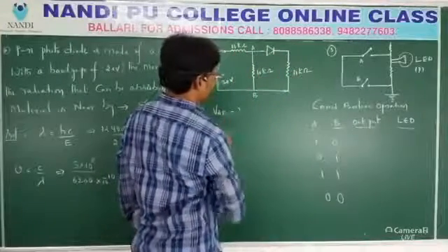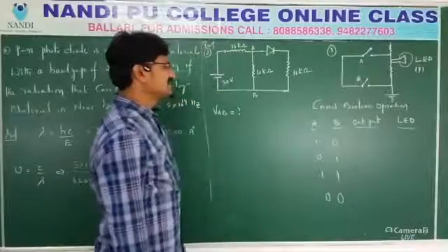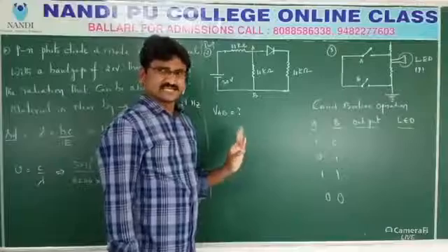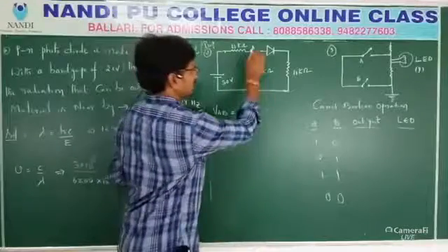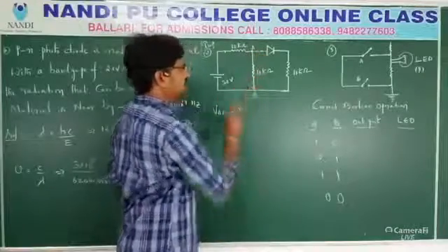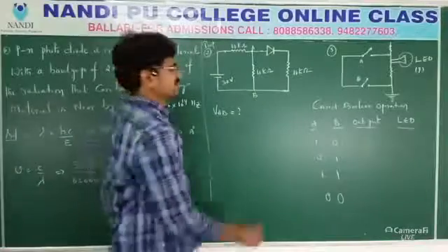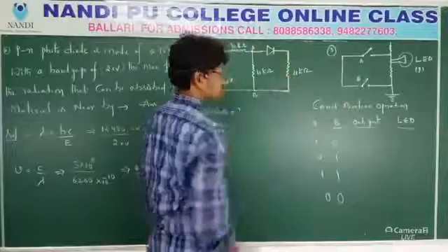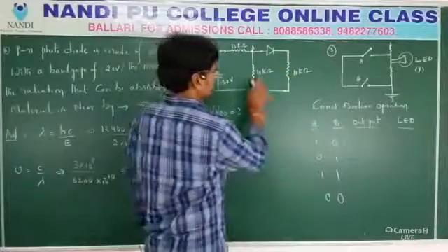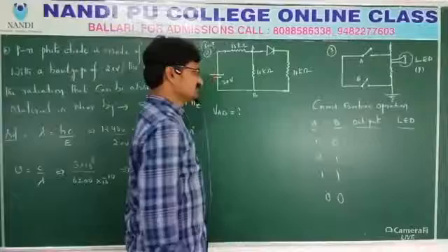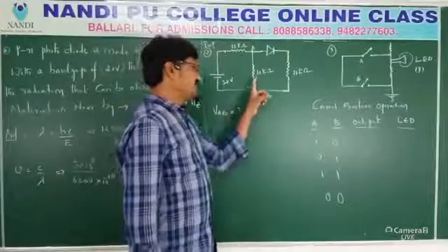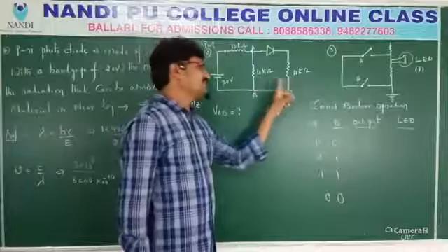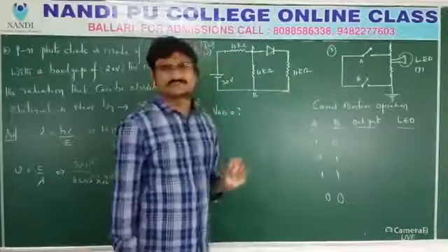So we have to find out the potential difference VAB. See, just like in current electricity circuit simplification, this is A, this is B, I have to find out the potential difference. Then from here, another resistance is there. So that it is 10 kilo ohm, 10 kilo ohm. The same potential is here also. Why? Because these two are in parallel combination.